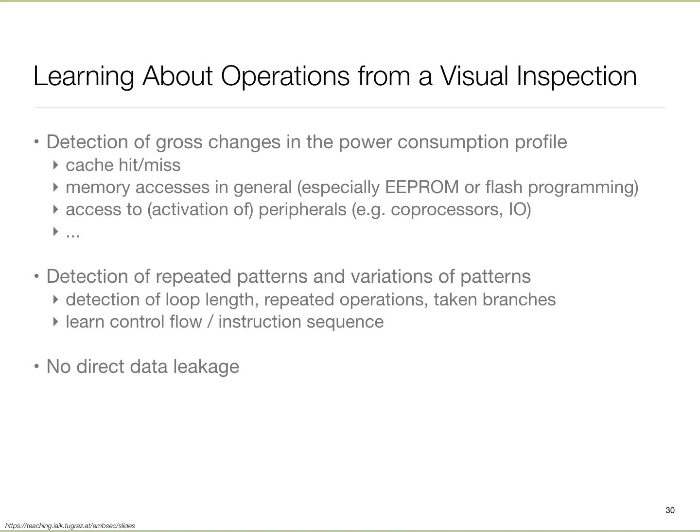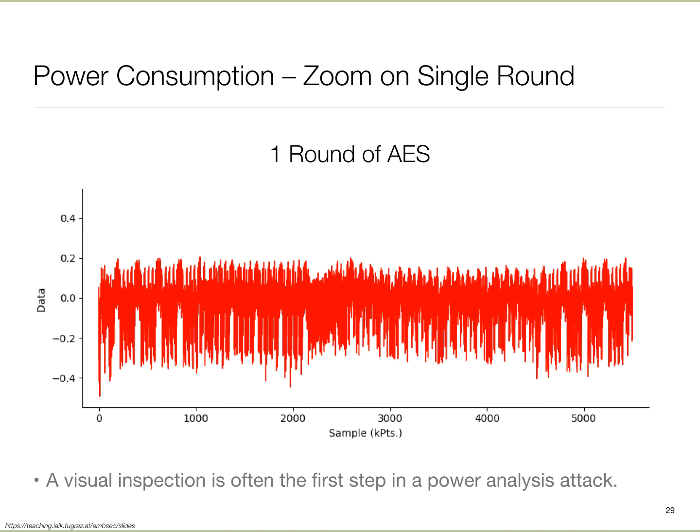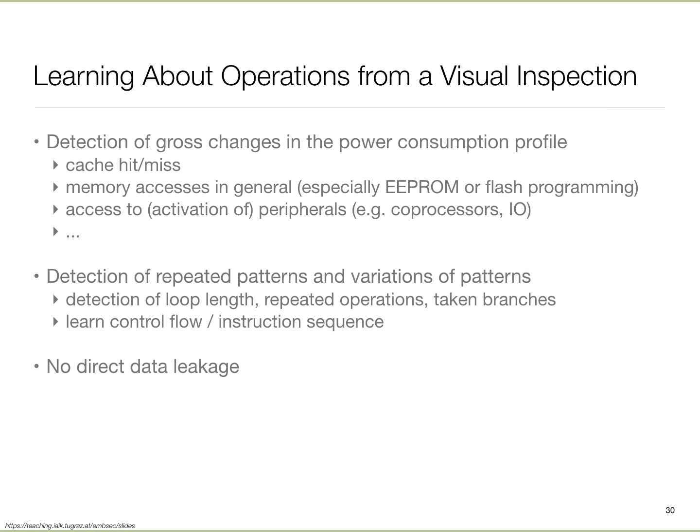You collect the data. Well, to collect this kind of data, all you really need is a storage oscilloscope, right? A scope which captures this, and then you are able to talk to a computer and extract this information. Nowadays, for pretty low cost, you can buy USB oscilloscopes which just let you capture stuff. There are many different ways, and there are also dedicated boards you can buy on Amazon. I have bought things for like $10. Alibaba Express usually has it even cheaper. They literally talk to USB, and they also monitor another USB line for power consumption. So you can do these traces super easily nowadays.